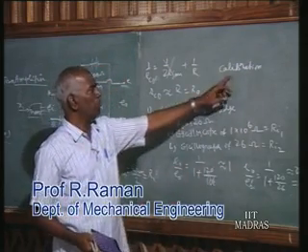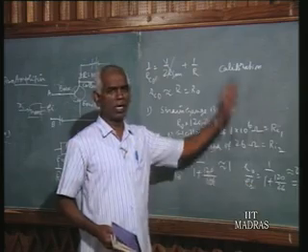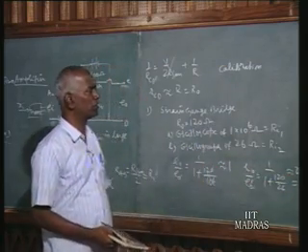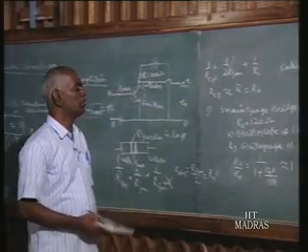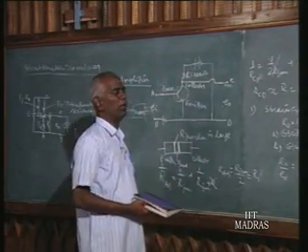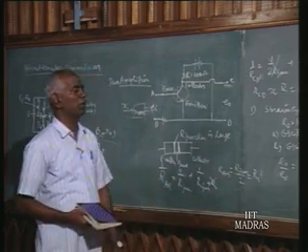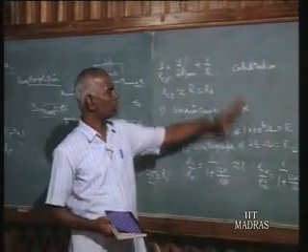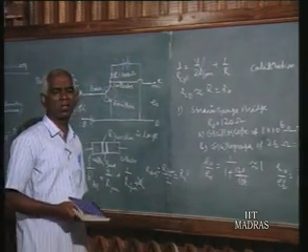But if you don't do the calibration, we say there is error. If you do the calibration, the error is removed. Since it is a constant error, we can always remove it by the process of calibration. So in the absence of calibration, you have to say the error is there, but once you calibrate it, there is no error. But if the loading effect is varying, is it possible to eliminate this error? That is not possible.